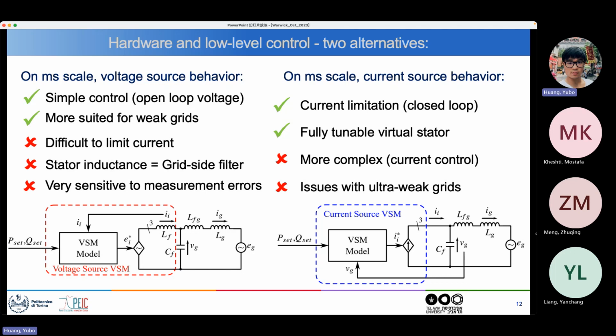Because the impedance of the output filter in a usual inverter is very small. Expressed in per unit, it would be something like 0.05. By contrast, the output impedance of a synchronous generator would be of the order of 1.5 per unit. That's a huge difference. So there are two reasons.